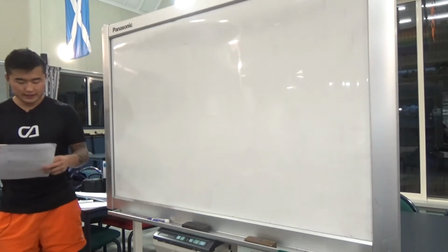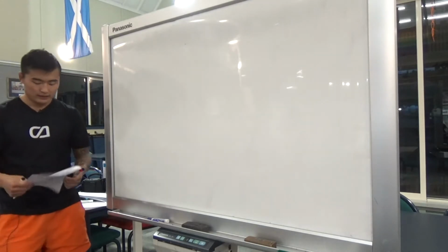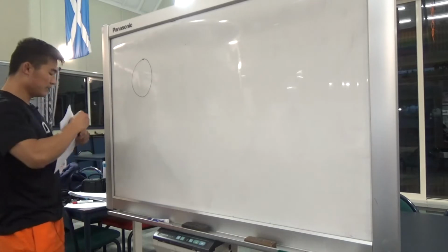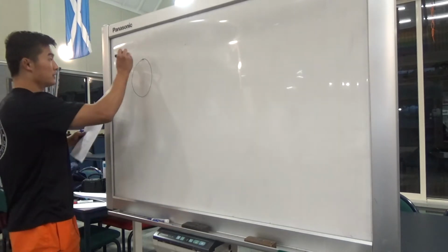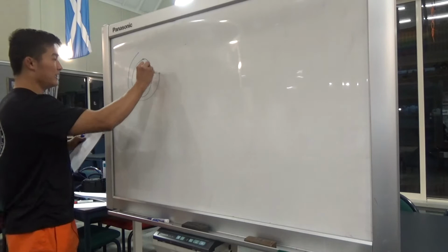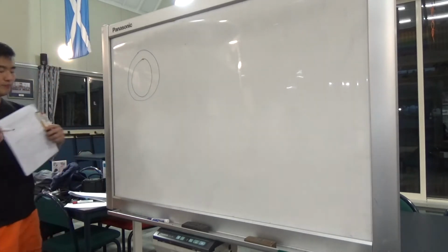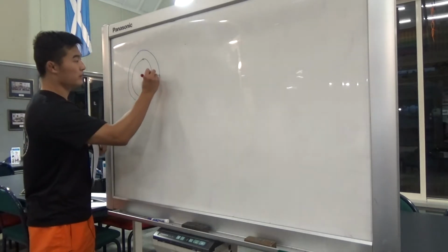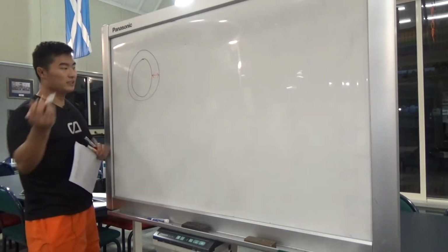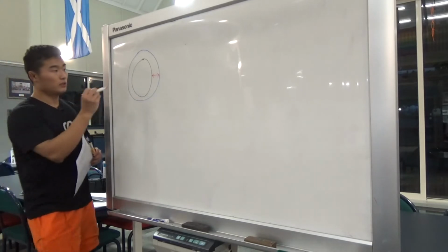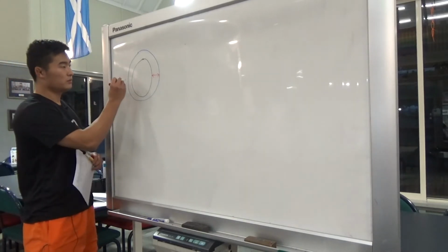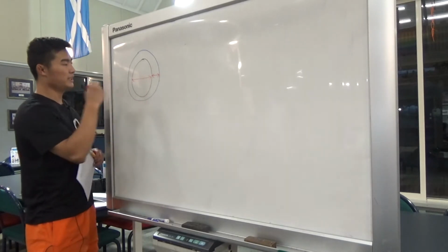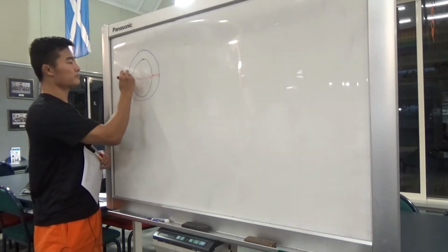Okay, so this is pretty similar to our last one. If we just imagine that this is the hole in the plate, it's going to absorb heat and it's going to get heated up. The diameter of this hole will increase, right?